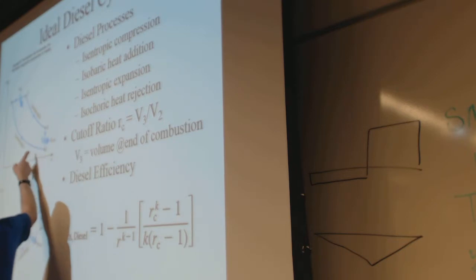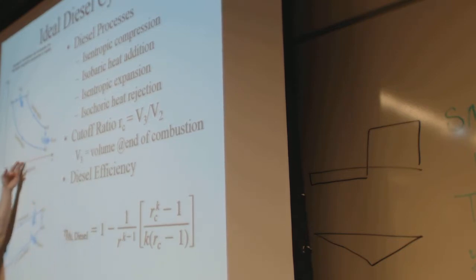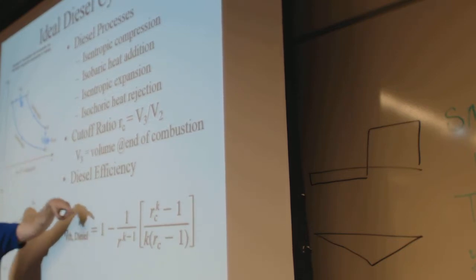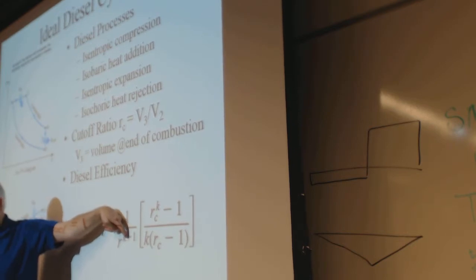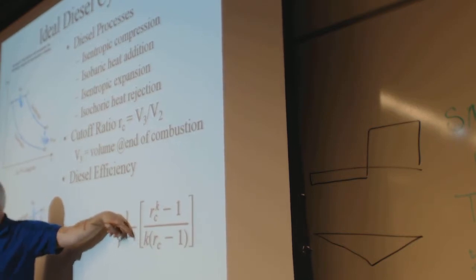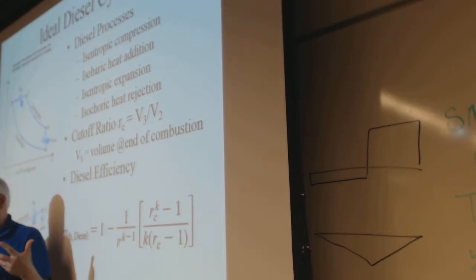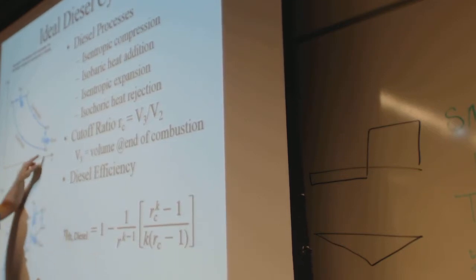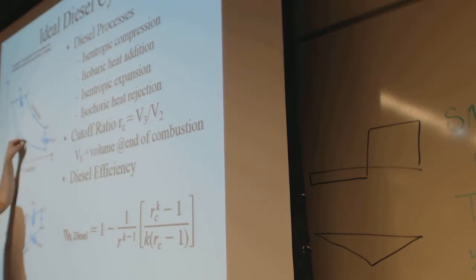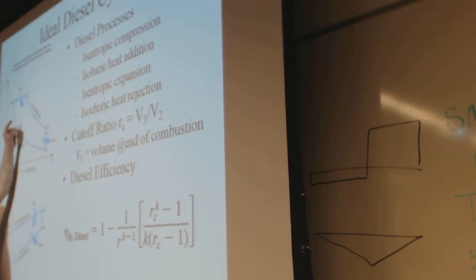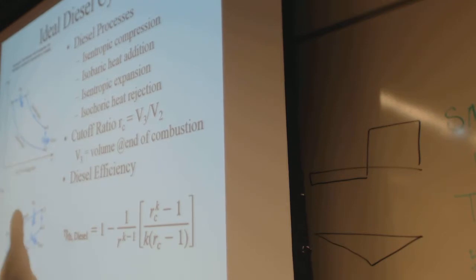So especially when we're analyzing these and we're using a formula that has a K in the exponents somewhere in there, that was derived using isentropic relationships. So it's going to be an isentropic value for the ideal gas. We're just using formulas. Remember, we're not using tables. Today you're going to have a steam one. The same concept.